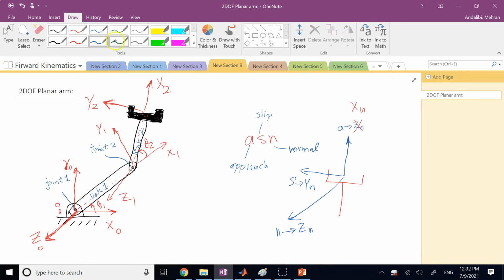The other thing is, here we really do not follow the fact that z is the actuation. Because as I said, these rules that z are the actuations for the joints are all for the robots themselves, not for the end effector. The end effector is not a part of the robot all the time, because one end effector can go, another end effector can come. And it doesn't mean by changing the end effector, I'm going to redo all of my forward kinematics. Absolutely not.